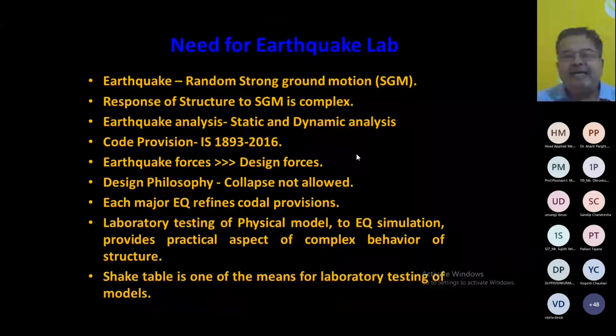Earthquake analysis we discussed in the last lecture, that we perform either static or dynamic analysis. We assume that the earthquake load is a static load, and then we perform the static coefficient method. We have performed the analysis through the static coefficient method, right? But this static coefficient method is more conservative. It will give you a higher value. So it is not a cost-effective solution on the other side, we can say.